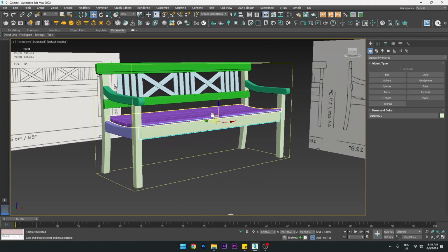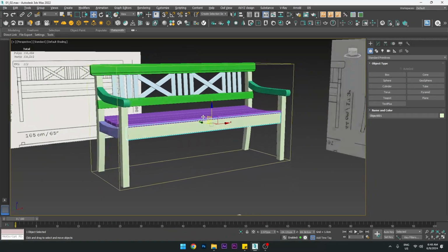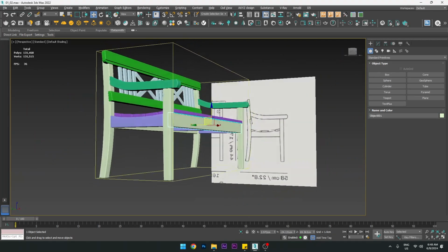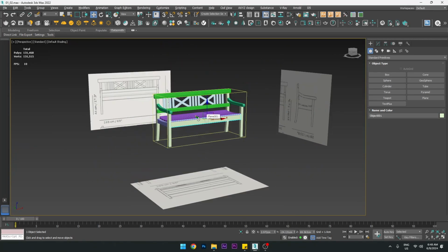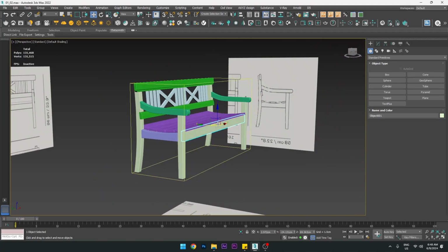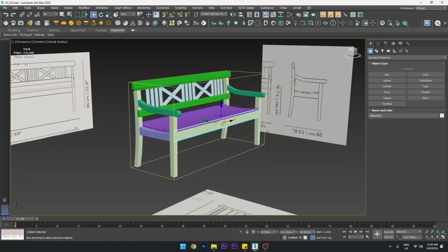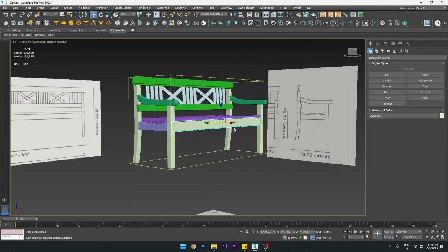Generally, I use both V-Ray and Corona in my workflow. As per the project needs, it can vary. So let's start with that. First and foremost, we'll be needing one studio setup. For the studio setup, what we will be needing first is the backdrop, and then we'll be adding two or three lights. One of them will act like a key light, and then the rest of the two will be mostly a fill or the rim light. That's how it will be.